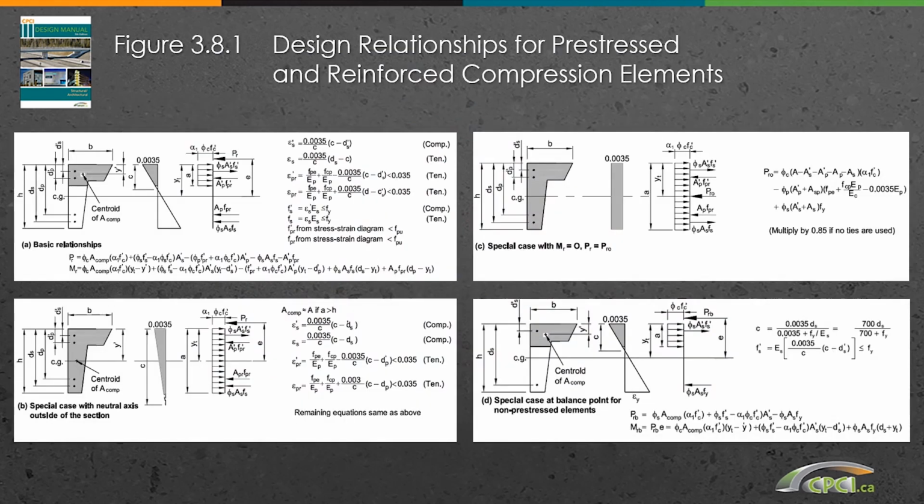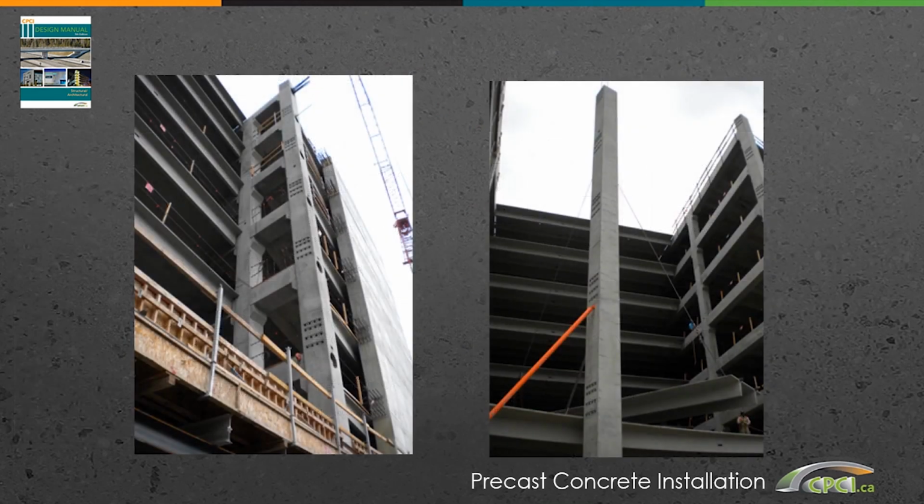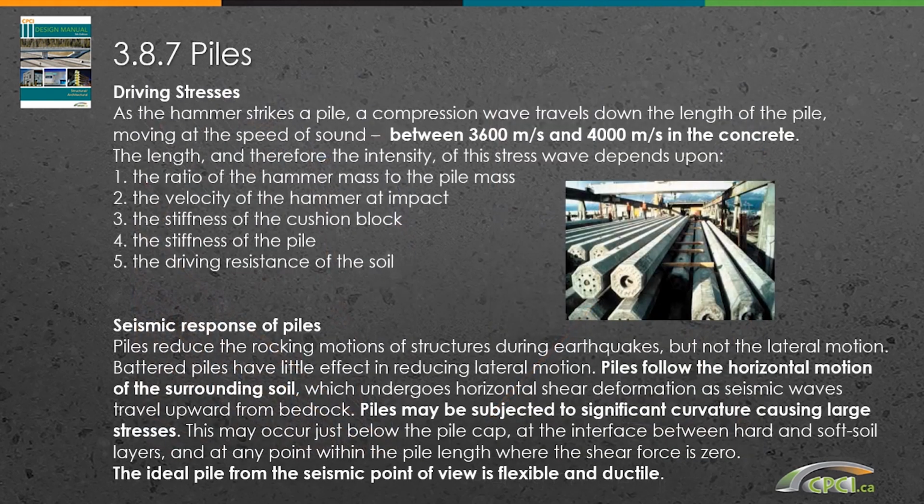We say that we pre-stress columns for one reason, because sometimes we have columns that long, and even though pre-stressing the columns will take away some of the capacity, sometimes when you need that length of a column, handling and shipping becomes a problem, and pre-stressing the column becomes a necessity, even though it takes away some of the capacity, but that can be achieved easily by adding more mild reinforcement or increasing the f prime c.